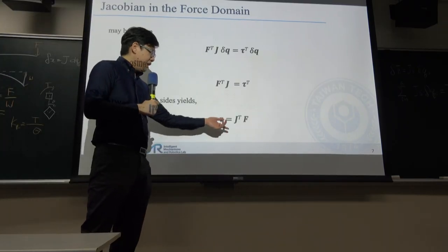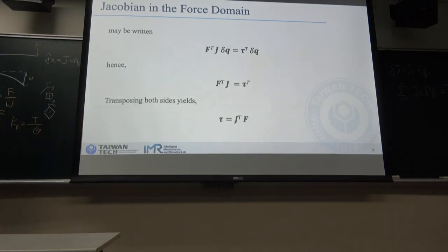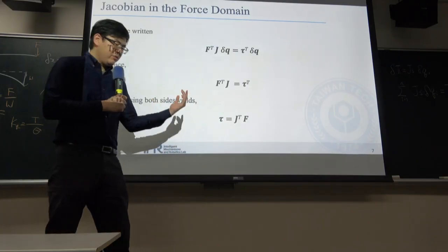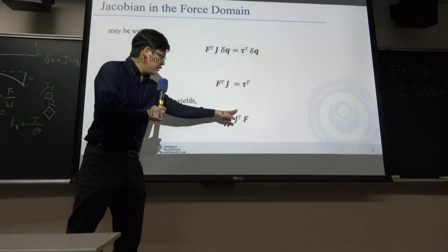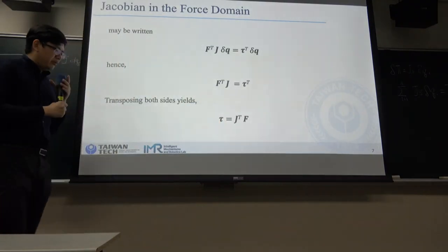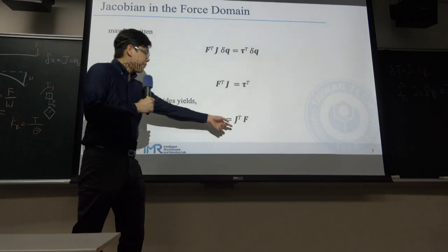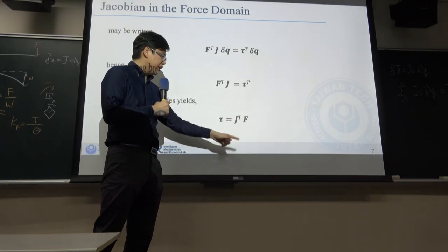Normally, as we have already stated, if we want to come to the force domain, we need to calculate the acceleration. But through the Jacobian and the principle of virtual work, we don't need to differentiate with respect to time to get the acceleration.